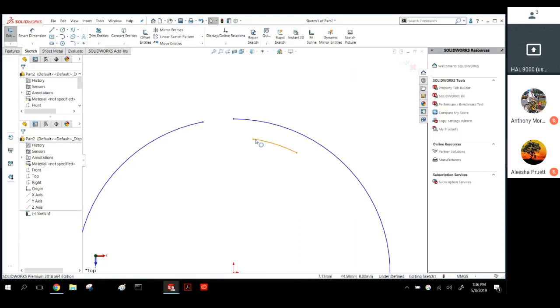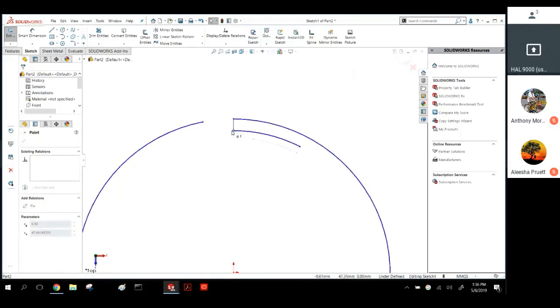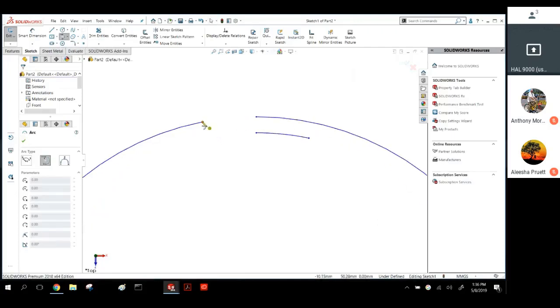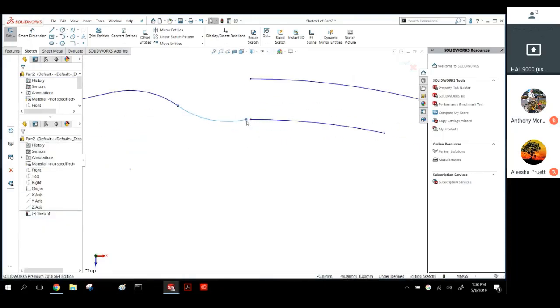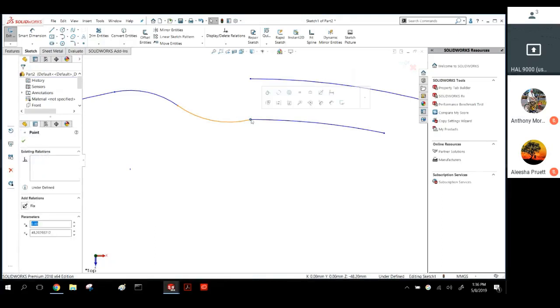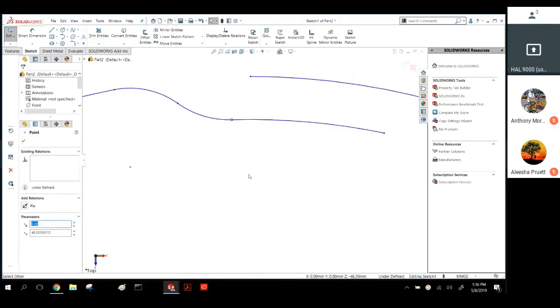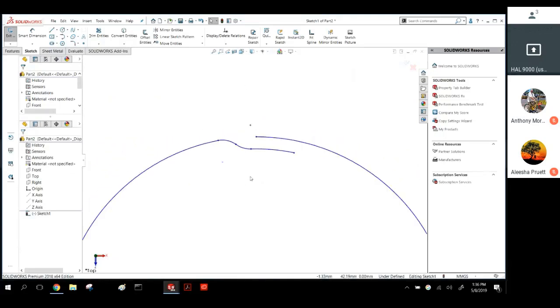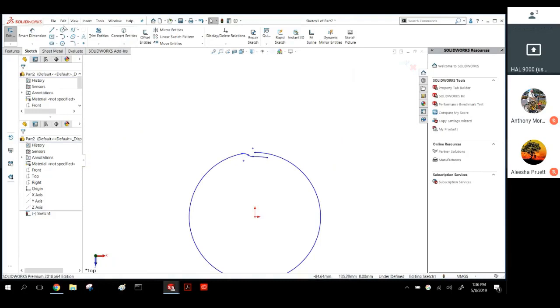So, all right, what I'm doing here is I'm going to create a shape here. Do some tangent arcs. I want to have this cylinder that's rolled, and I'm going to have it overlap so that I can have a really strong seam here. Just a trick, if you pick a point where a line and an arc come together, make those tangent rather than having to pick both items like you used to in earlier versions of SolidWorks.